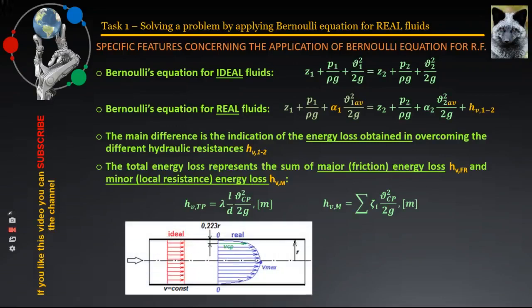It can be seen that if ideal fluids existed, the velocity distribution in the cross-section would be uniform, which means that at any given point of this section, the velocity would be a constant value. However, this is not the case with real fluids, where the velocity just next to the walls is zero, and the closer you get to the center, it starts to increase.